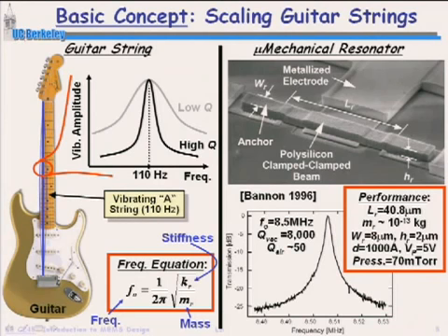It has to do with the reactance you can generate in a certain element versus the loss. Q, the quality factor, is energy per cycle. So think of something vibrating. It's got a certain amount of energy while it's vibrating, divided by the energy lost per cycle. The energy losses come about in a mechanical system because the anchors are radiating energy into the substrate. For this device, it's going to be air damping, which I'll talk about in just a second, to get that 50.